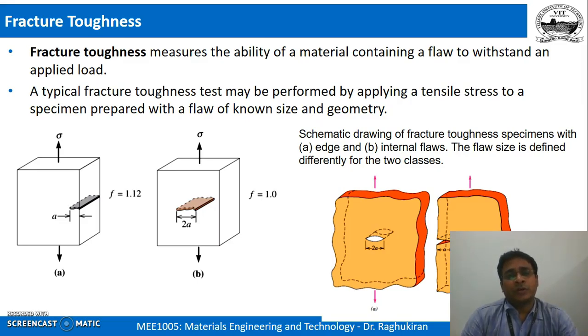A combination of all this is typically the scenario, right? Now the question is, can an engineer assume the load is applied gradually and design the components based on yield strength alone, or should we actually bother about the real scenario, such as a complex loading condition, and then design the components to withstand such uncertain loading conditions? So definitely the answer is yes. You have to take care of all these uncertain loading conditions, otherwise the material will simply fail. The component will fail.